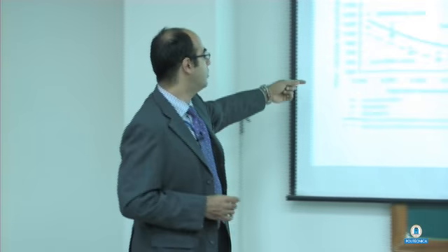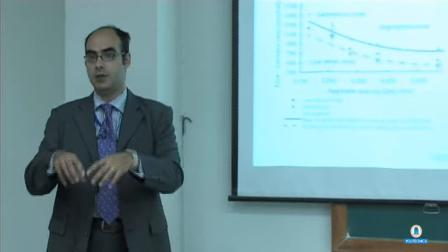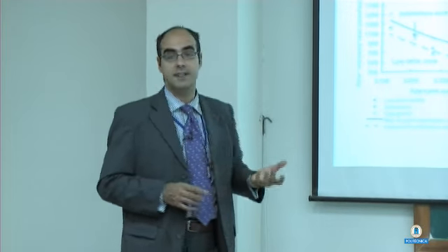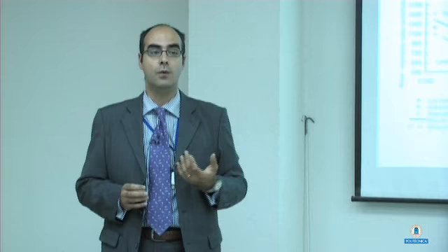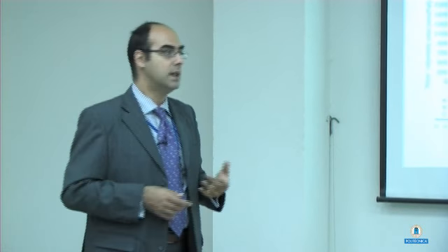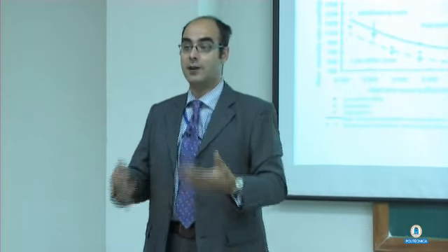This is the ratio between the flow diameter as measured with the mini cone test and the viscosity. The viscosity here was measured with a rheometer, but this is a quite demanding test. If you want to do quality control in a factory, you cannot prescribe rheometer measurements all day. So we are now working on alternative, let us say field-friendly, methods.